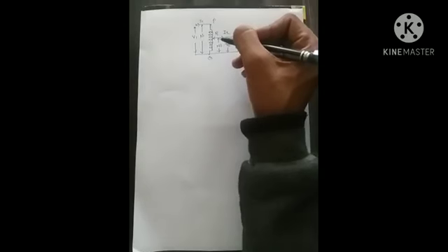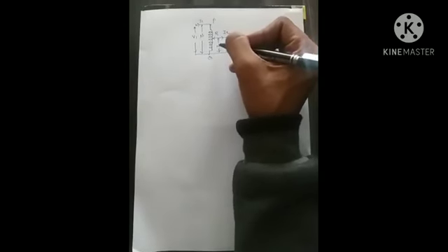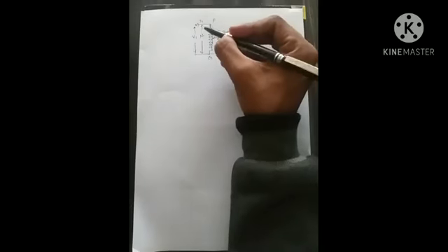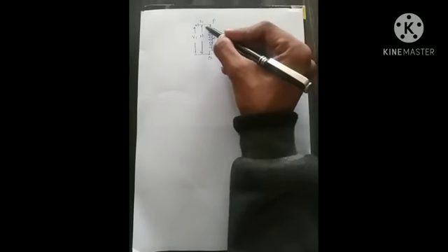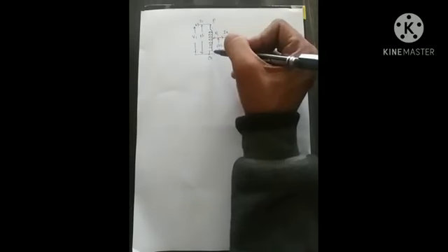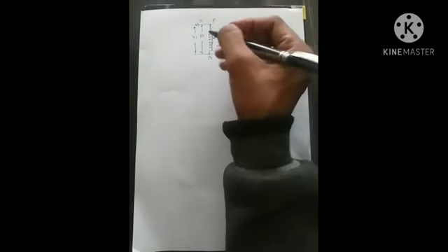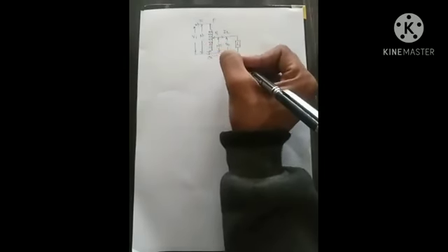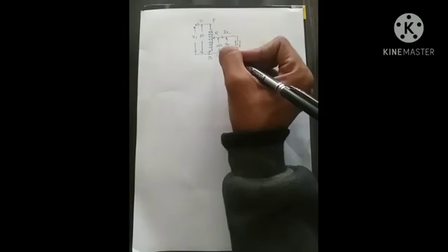The cost of the transformer depends upon the volume and weight of the copper. So the length of each turn of winding of the auto transformer is considered as L, and the current density is considered as J. The current distribution is shown in the figure. I1 is the primary current which flows through the main winding, so the current from Q to R is called I2 minus I1 current.